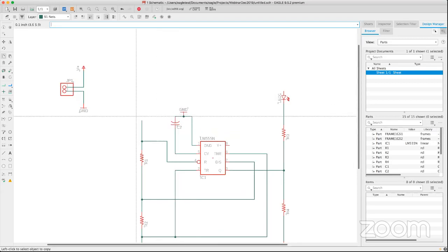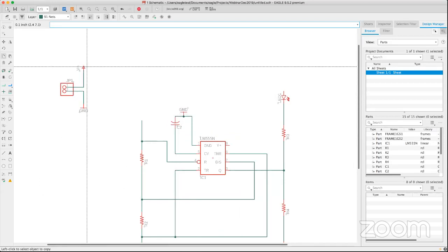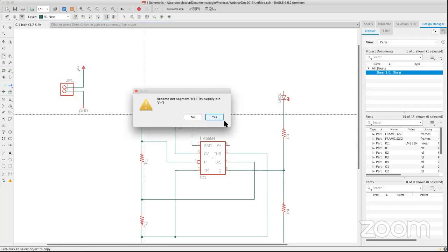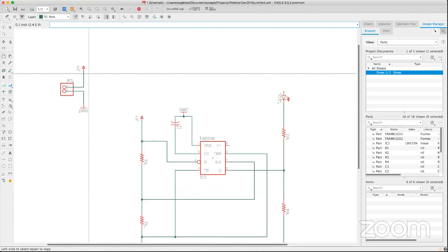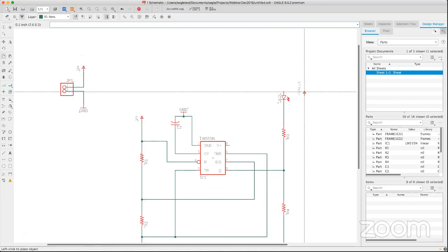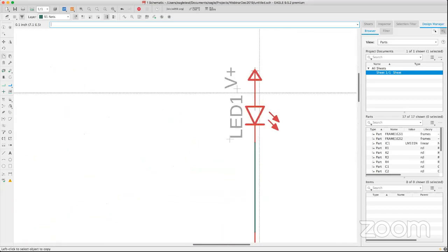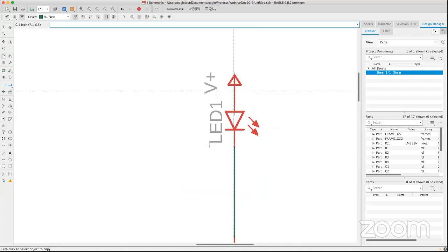Now this side is connected to V plus. So I'll go ahead and make a duplicate of this one, and say that one needs to be connected to V plus. I'll make a duplicate of this one, and this needs to conduct V plus as well here. That's where that's going to be connected. Now you'll notice that I put one pin to another pin together. You don't see a net, but they're actually connected.